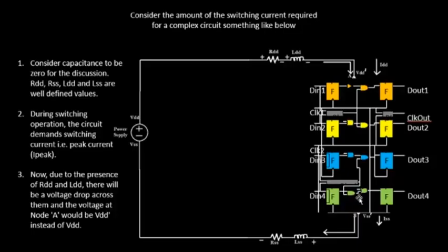Basically what happens is there is a small capacitance sitting over here, and whenever there is a transition from 0 to 1, this capacitance has to completely charge to represent logic 1. The amount of charge for this capacitance will be sent from the supply voltage. So it's the responsibility of this supply voltage to supply the necessary amount of current to this logic and to all other logic whenever it is switching from logic 0 to logic 1.